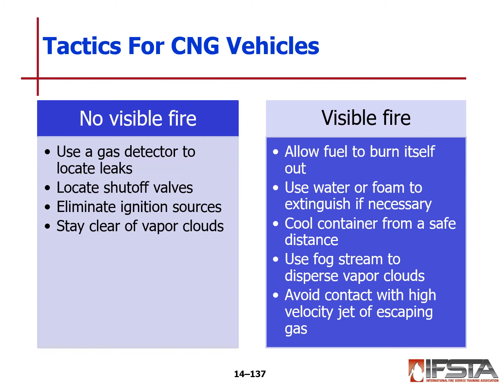With these types of vehicles, there may be no visible fire. You may have to use gas detection to locate leaks, locate shutoff valves, eliminate any ignition sources, and stay clear of any vapor clouds. We would approach it much the same as a gas leak. We may be wearing our SCBAs the entire time and using monitoring equipment.